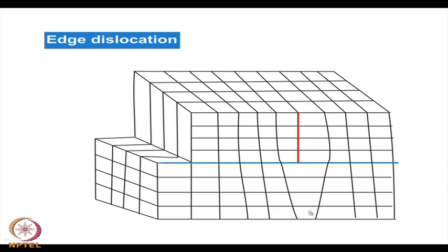On the right the atoms have no deformation, and so there is a boundary between the slipped region on the left and the unslipped region on the right. So, that is what it refers to. So, this is an extra edge of plane, edge of atoms, which is called an extra plane, right. This has been compressed, the top part has been compressed, the right bottom part has not been compressed, right. There may be slight deformations because there is an elastic deformation, but there is no plastic deformation so far.